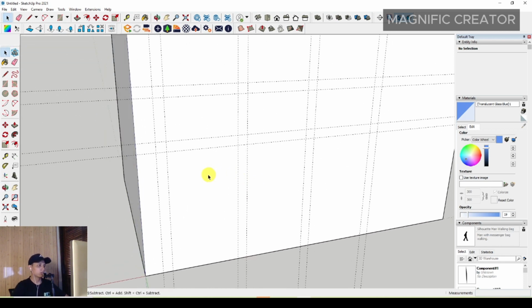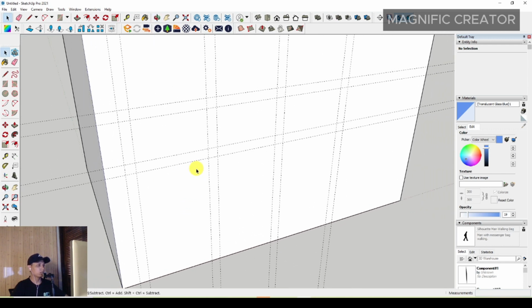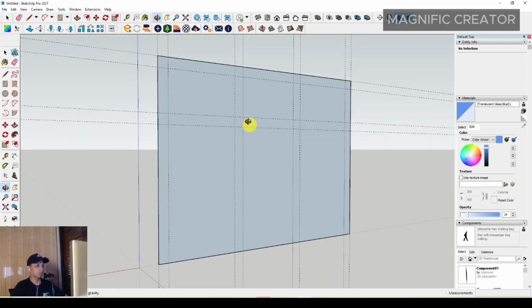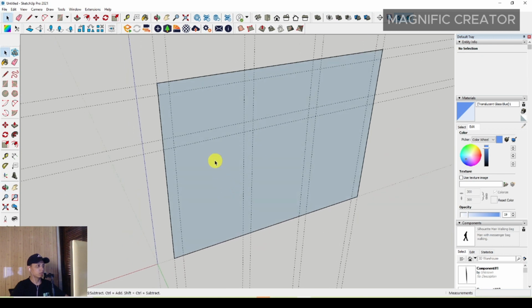Okay, and then you can make a wall or structure first with a rectangle right here. So you have to delete this. Now you have this arrangement between a rectangle and a guideline, and you can select this rectangle to make a door opening. Just use a rectangle to make the window opening also.